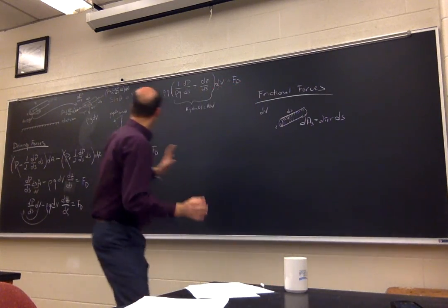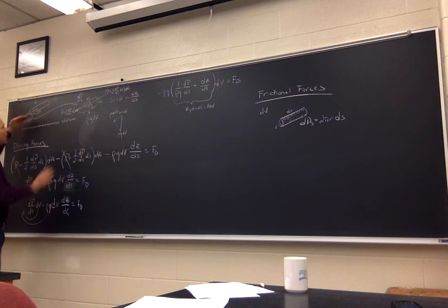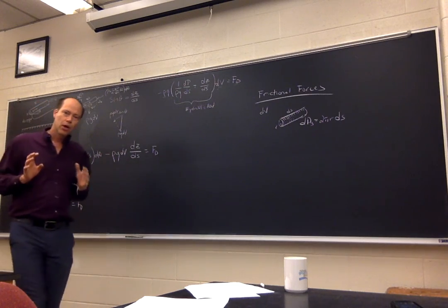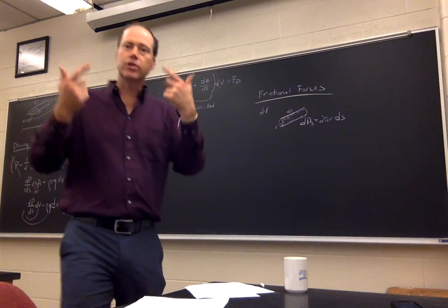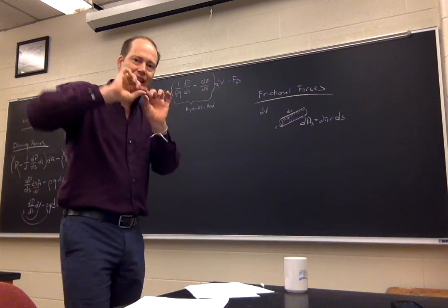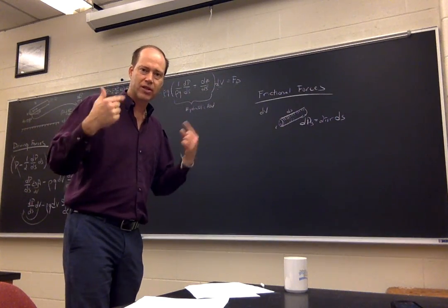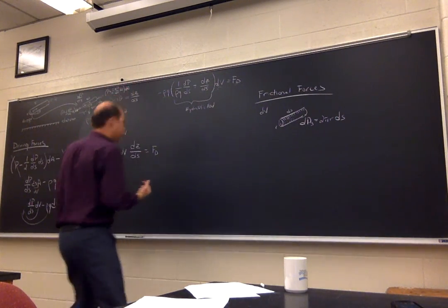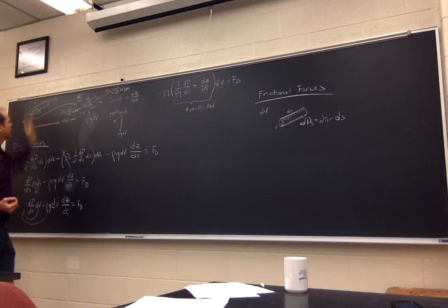If we go back and look at the problem, remember that in order to assess the amount of water coming through, the hydraulic head is what's driving it forward. But what's slowing it down and causing that pressure differential is the frictional forces acting on that water, primarily on the boundaries of the pipe.